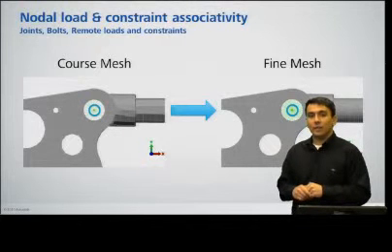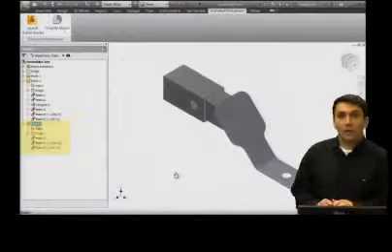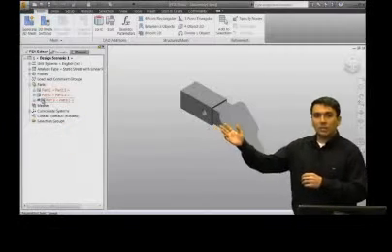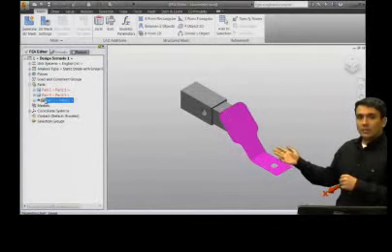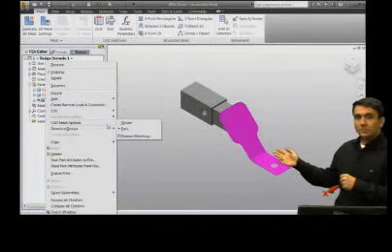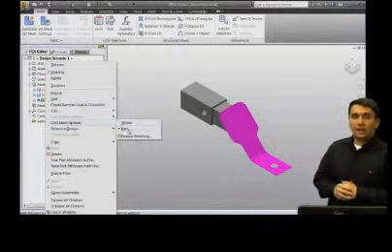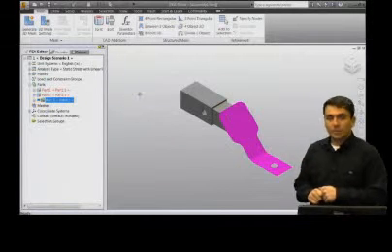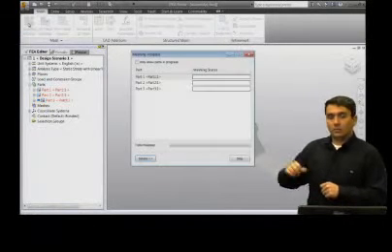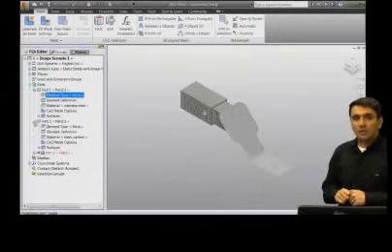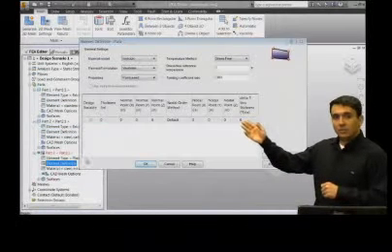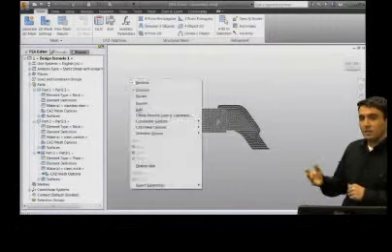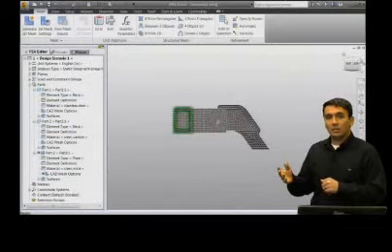Now let's take a quick look at how this works in the software. Okay, here I have an Inventor assembly, and it is made up of multiple solid objects and surface objects. Those surface objects come into Simulation Mechanical 2014, and the mesh type is automatically set as a part mesh object, and it is set to plate shell, as you can see, which allows me to just simply click the Generate 3D Mesh button, and it will automatically assign brick elements to the solid objects and plate elements to the surface object. When I define its thickness, I'm essentially ready to set up the rest of my analysis.